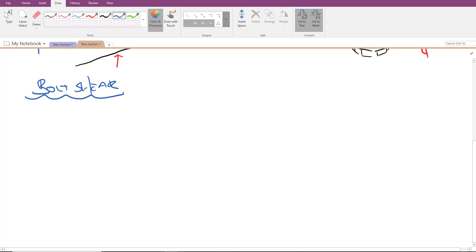Determine what the capacity is for the bolt condition in the shear failure. So P over NA has to be less than or equal to Fv, meaning the allowable shear stress. Notice in this case, this is the actual shear stress that we're working with here, and we just want to rearrange it and solve for the equivalent load that'll cause that.